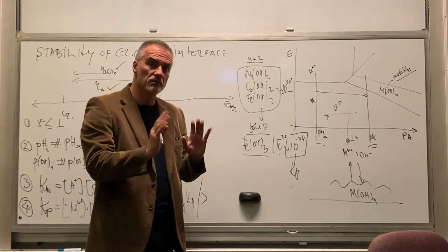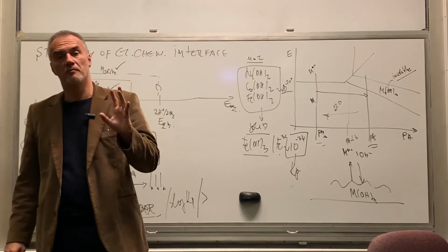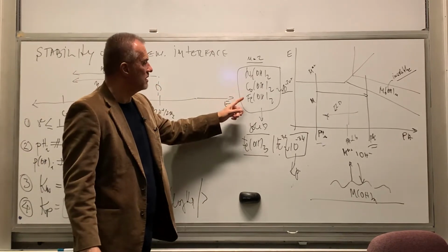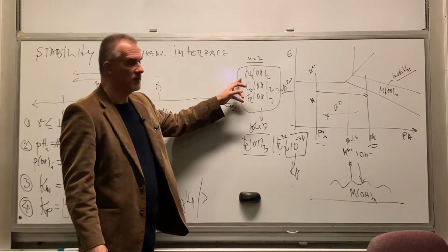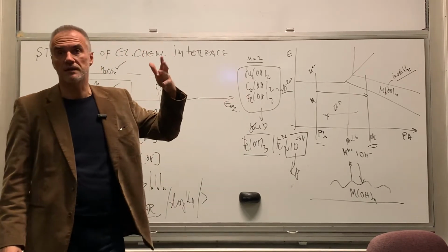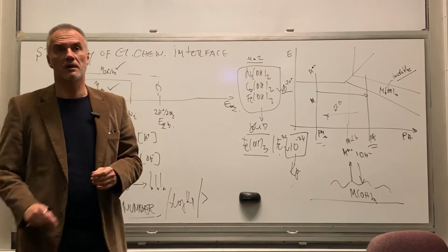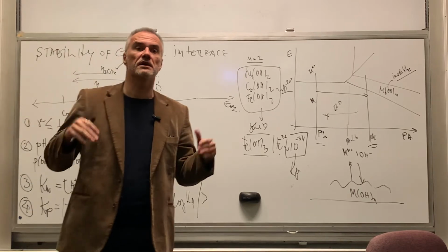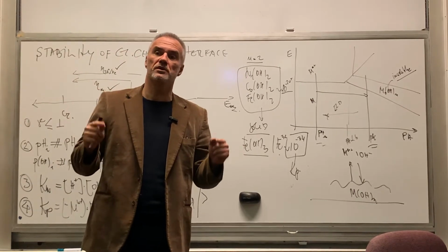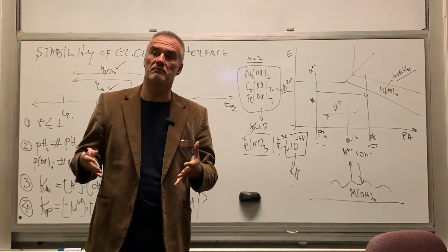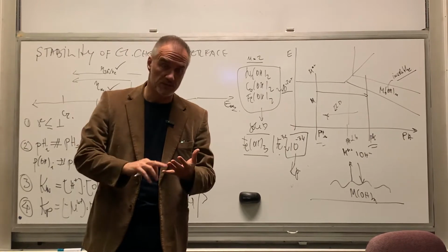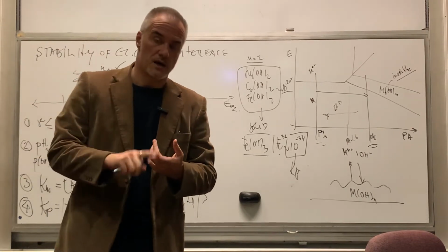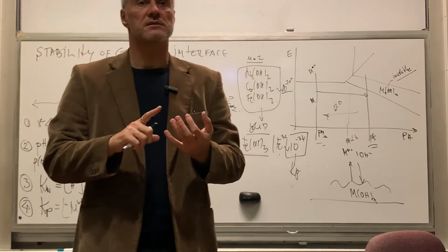And what that really means is that you're getting a mix of metal phase, which for these is either BCC or HCP or FCC, plus some oxide in there. And if you do XPS or EDS analysis, you're going to realize, wow, I have a lot of oxide in my deposit. So your deposit is not acting like a pure metal. What does it affect? It affects magnetic properties, coercivity, magnetic moment, hardness, stress, all sorts of stuff.